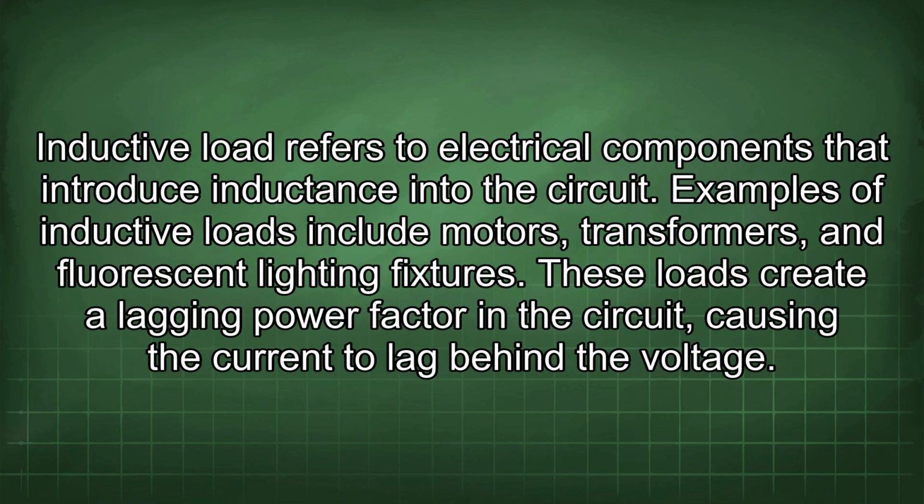Inductive load refers to electrical components that introduce inductance into the circuit. Examples of inductive loads include motors, transformers, and fluorescent lighting fixtures. These loads create a lagging power factor in the circuit, causing the current to lag behind the voltage.